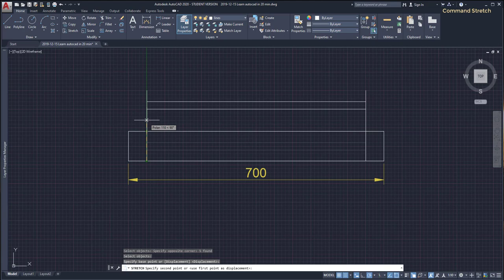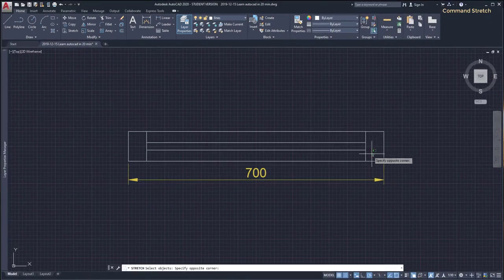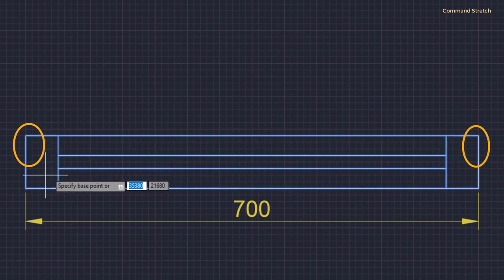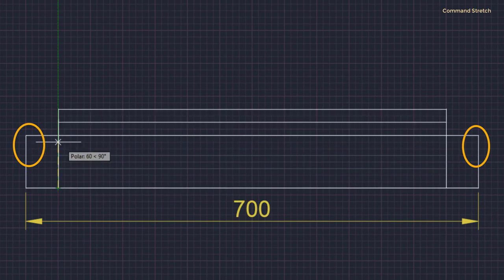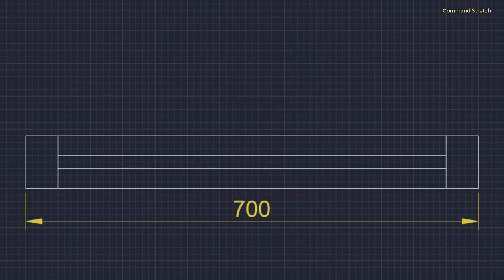But I select all the objects. Why does this happen? When I was doing the selection, I kept these sides outside of the selection area. And even so everything was selected because the external rectangle is a polyline, a single object. The really important thing here is what actually I am covering with the area.